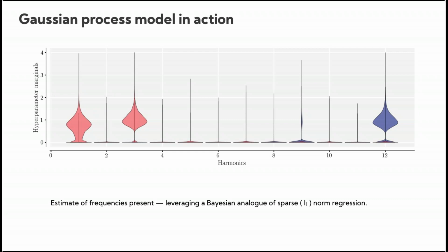very, very involved, especially for a real engine experiment, to understand a lot of the bits that go in. So ultimately, we do get a precision estimate, but we're also able to get a breakdown. Like this much of the uncertainty was associated with static calibration, this much with the recovery, this much with just the length of the wires, which creates a certain uncertainty as well.